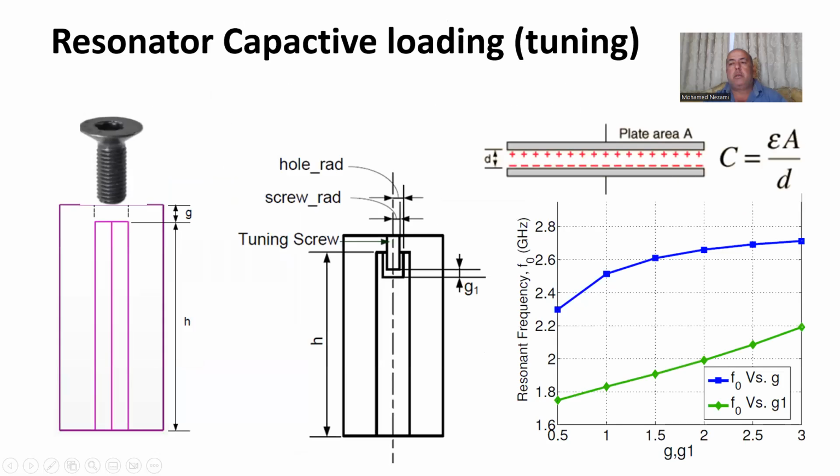Okay, so here is how physically most of these filters are implemented. We've got a screw that comes in from the side and drills down against the resonator. And you can tune the electrical length of this resonator by adding more or less capacitance using this screw, okay? And another technique which they use, so if you do this, let's look at the blue line, and I took this out of the IEEE conference papers. Unfortunately, I didn't copy the reference here. I could always give it to you.